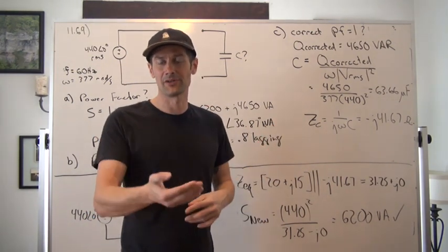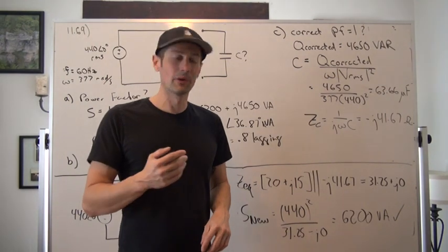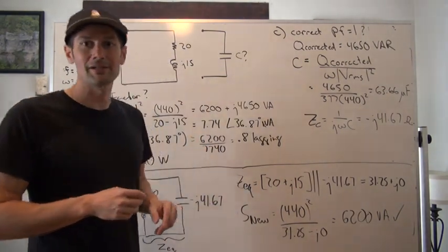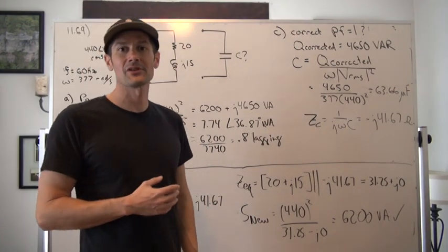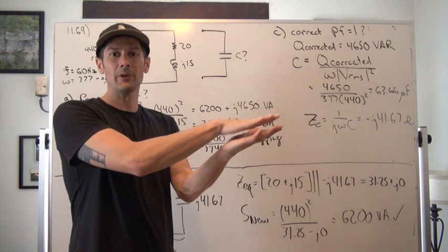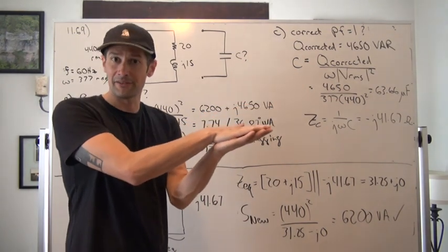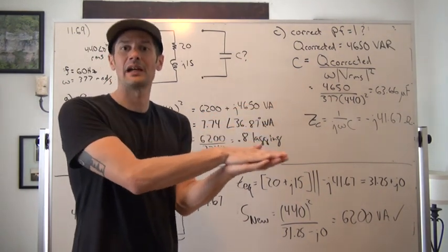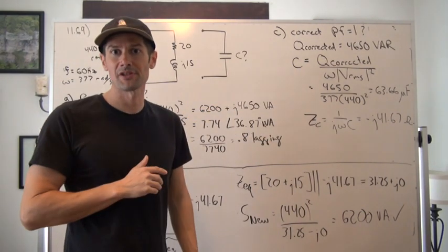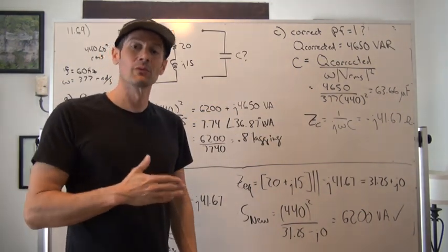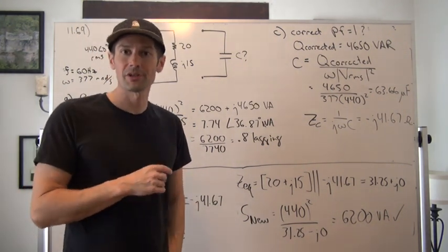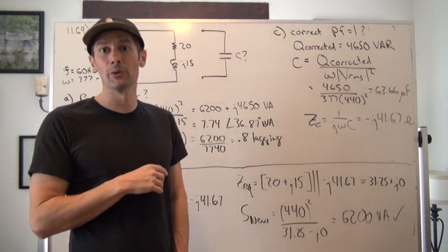And so we know the cosine of 0 is equal to 1, or in this case, the ratio of real power to apparent power is just equal to 1, meaning that we've taken those two phase angles of the voltage and current and caused them to come together, meaning that they're in phase, which means that we have a mostly or almost exactly resistive system. I like saying mostly because we're still going to have an inductor in there, we're still going to have a capacitor, we're just going to cancel out the effect of both of them.